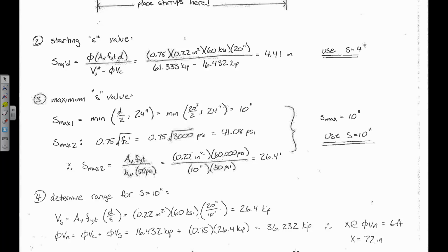So how would we lay this out? Well, I've got one at 2 inches, so how many do I need at 4 inches? I'm asking you. 18, right? Look, you can look at the page, but I want to make sure, because I could be wrong. I'm not perfect. So this is 18, which is 72 inches, because that gets you to x equals 2 inches, and this will get you to x equals 74 inches. If you used one less, that'd be x equals 70, and it isn't far enough.